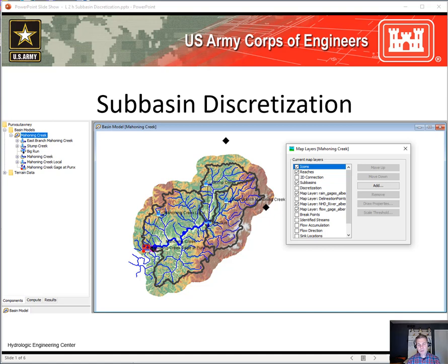And so in addition to subdelineating the subbasins, HMS also allows you to define a grid or a mesh that you overlay on top of the subbasin elements. And then that grid is used to get information like gridded precipitation. So if you have radar rainfall, satellite information, you could apply that, and that grid that you define, that discretization of the subbasin elements, is used to intersect those cell centroids with that meteorologic data to determine the representative value for that cell.